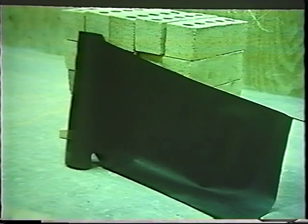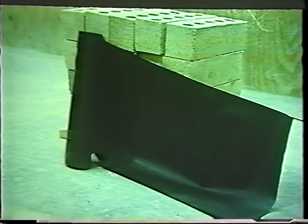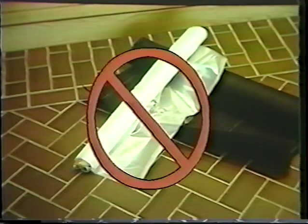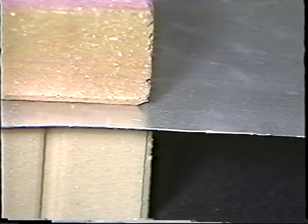Thicker flashing materials should be used since they will not puncture easily and will last longer than thinner flashings. Building felt and polyethylene sheet should not be used as a flashing material. They can be easily punctured and deteriorate quickly. Aluminum should not be used. It corrodes in fresh mortar.